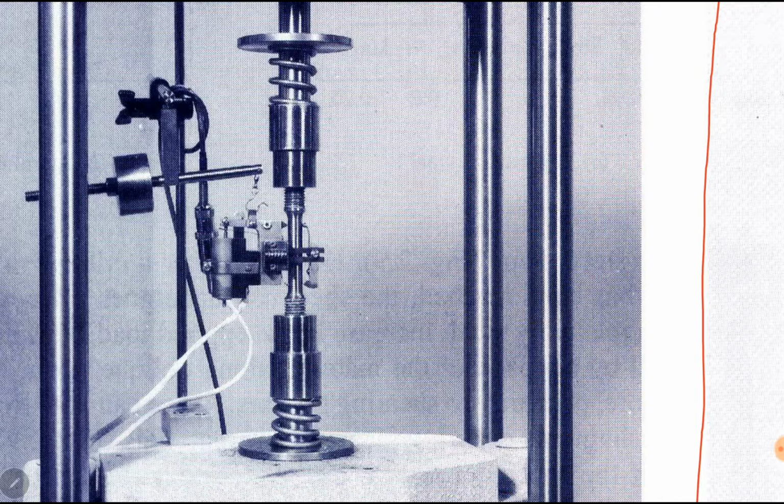The next is the displacement of point D. If we consider the member CD, it is under tension, already established. FCD is known, A is given, E is given, length is given.